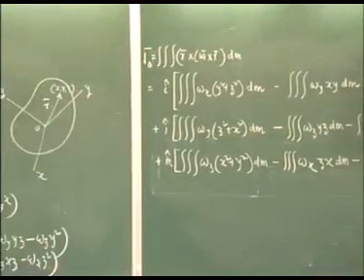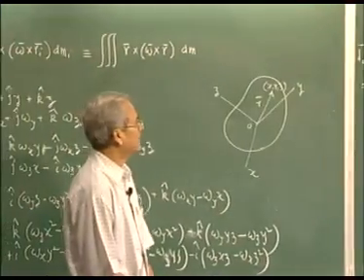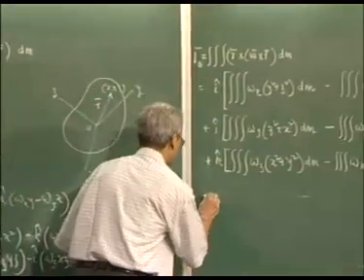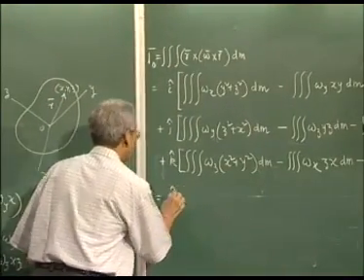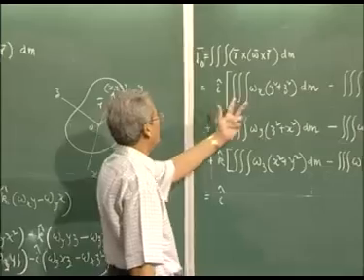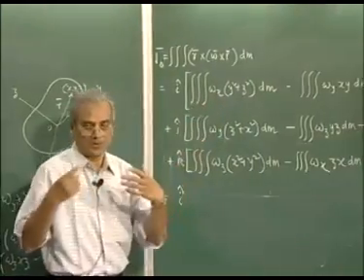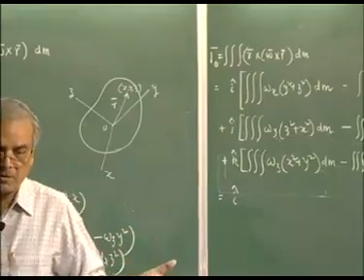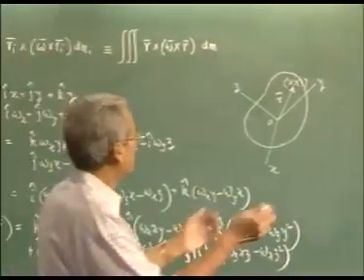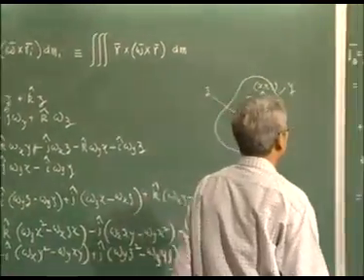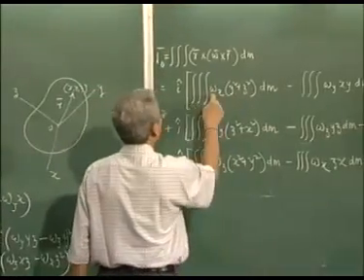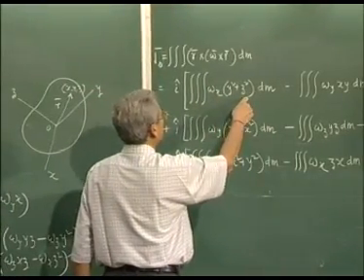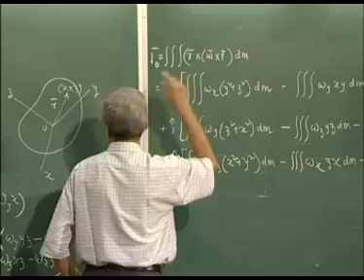Now, let us see what we have got. Here, if we further examine, we will find this is nothing but i. Now, the omega x component of the angular velocity of the rigid body does not depend on the particle, so it can be taken out. If I take out this, then what remains inside is dm into y squared plus z squared.